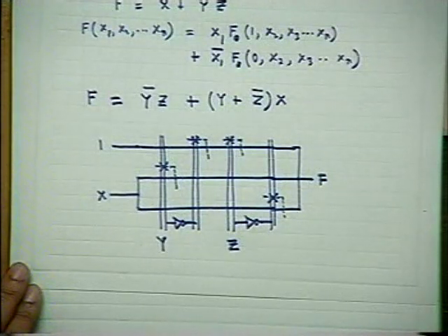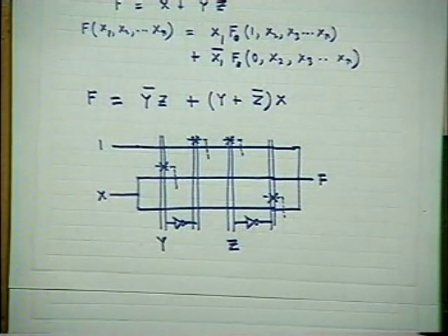Therefore, you see that pass transistor logic is a very good concept. It can be used for realizing combinational logic in a very simple fashion, in a very low cost fashion also. But when the size of the chip is larger, when many variables have to be handled, then it becomes difficult. Otherwise you can use CMOS gates. But CMOS gates technologically are more complex. It is used in combination with a normal inverter. We shall be coming to that afterward. Just pure pass transistor logic today has very limited application because of developments in other areas.